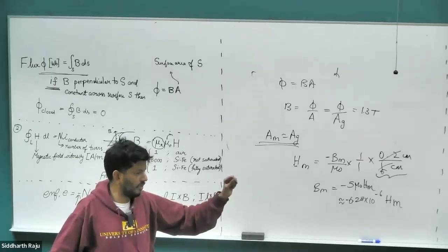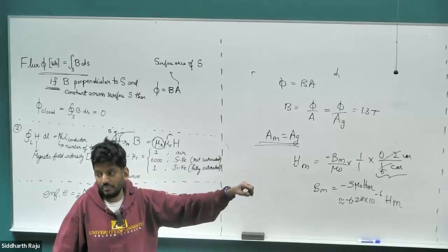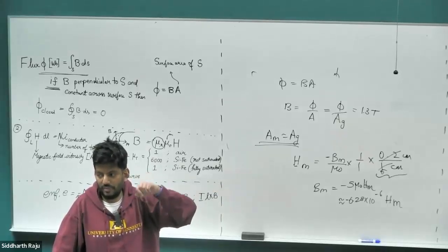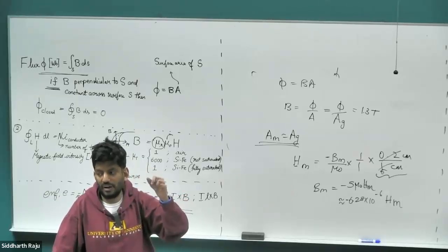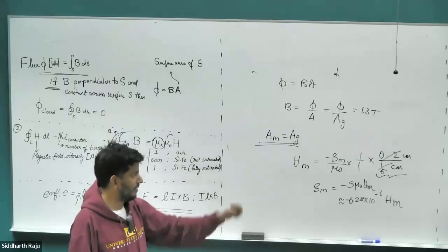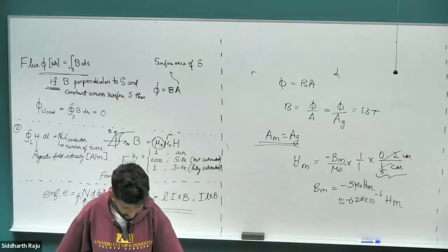But the reason we want to go to a smaller air gap is because the magnetic field starts to exponentially drop, particularly in permanent magnet synchronous motors. That's one of the biggest problems, right? Why we use interior permanent magnets. When you have surface permanent magnets, you need a little bit larger air gap because once it rotates, it can get pulled out and so on and so forth. So yeah, that's a very big design challenge that needs to be addressed. Any other questions?